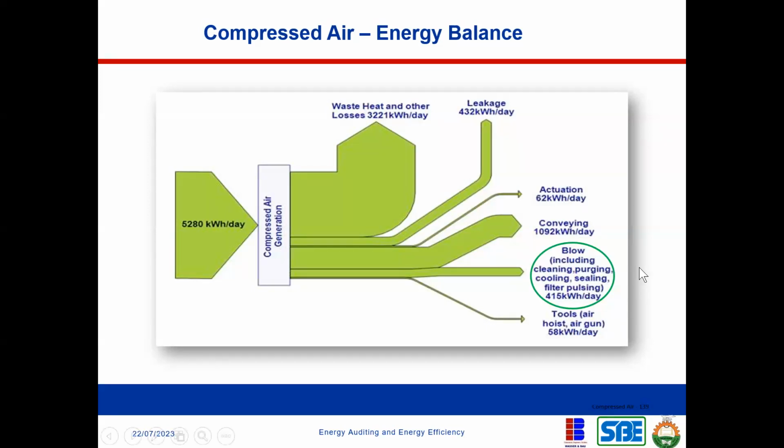And in compressed air system, there is high opportunity to recover waste heat. Compressed air system has a waste heat area where you can actually recover some of this waste. So that's 80% that is being wasted. Most of them are being wasted as a waste heat. So you have to see opportunity to recover those waste heat. And that's what you can see here.